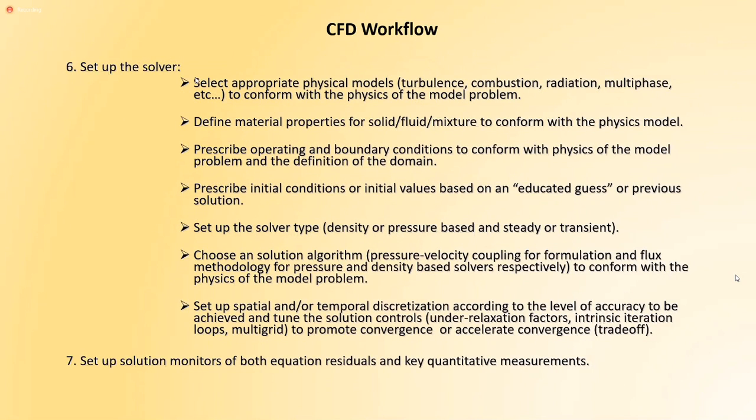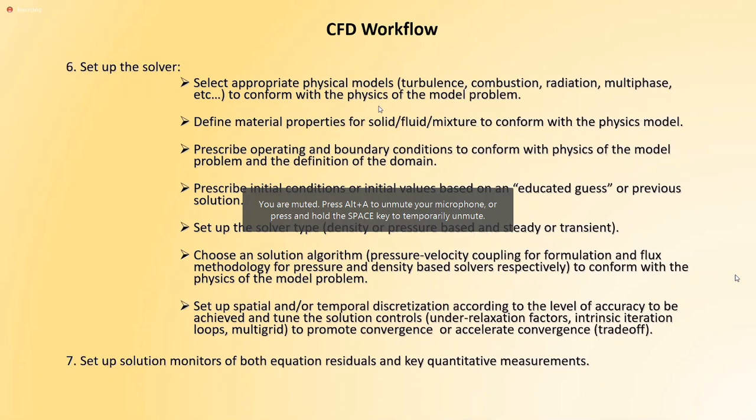Still in the CFD workflow: set up the solver. The solver is very important. Select an appropriate physical model, of course. In Fluent, there's a viscous button, where you choose whether the flow is laminar, inviscid, or uses some turbulence model. If you need combustion or radiation, it needs to conform with the physics of the modeled problem.